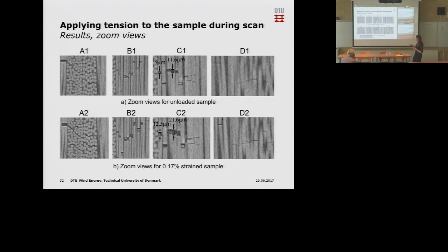Now in the unloaded state and the loaded state, you can see that there are some off-axis cracks in these backing fiber bonds that become a little bit more visible, though it's maybe difficult to see. And if you compare these two images, you can also see that there are some fiber fractures that were not so visible up here, but they're actually quite visible here with load applied.